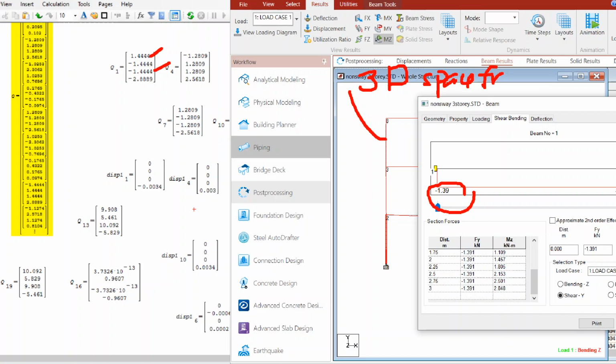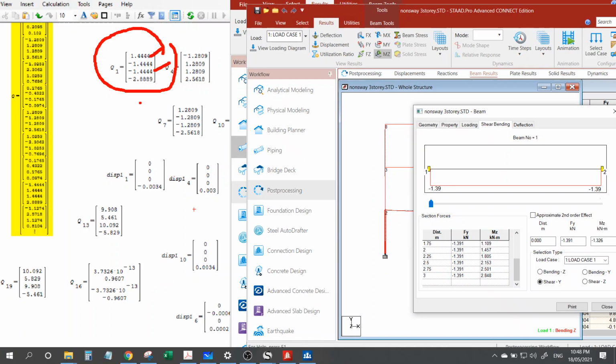Okay, and as you notice, we just use a beam stiffness formulation, and we almost get the same answer, because that means our assumption of a non-sway frame, of neglecting the actual stiffness and actual deformation, of course, and other degrees of freedom is still valid. Okay, so therefore you can analyze a multi-story building using just a stiffness matrix formulation of a beam, as long as these assumptions are still valid.